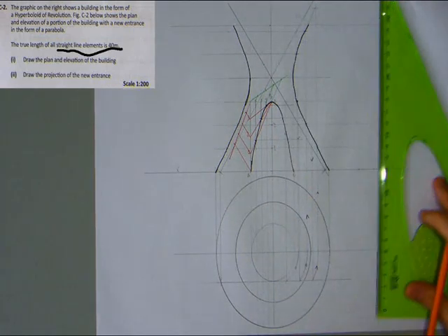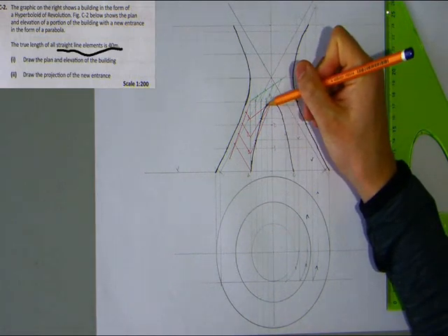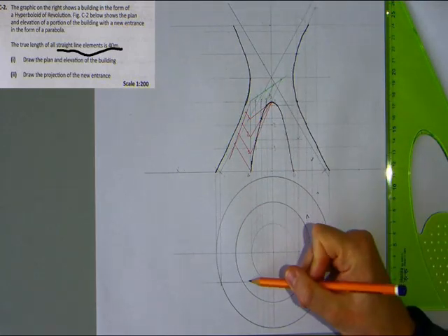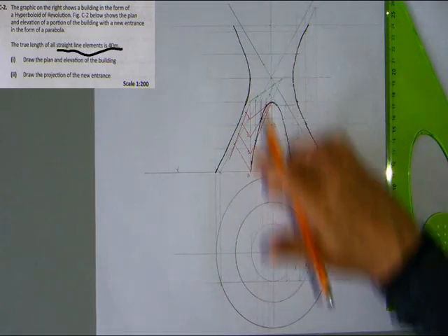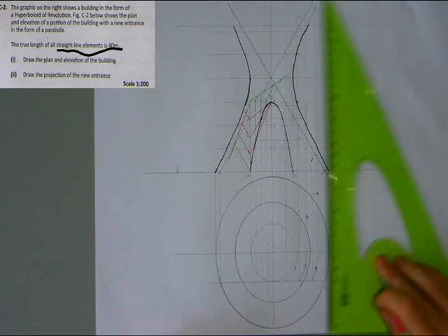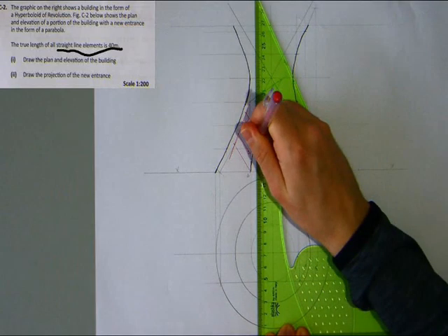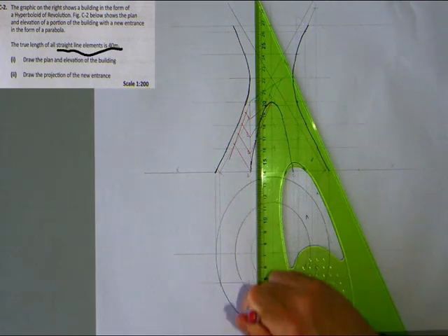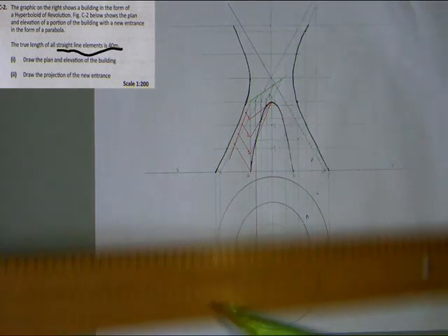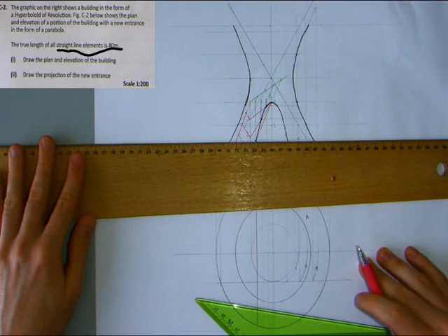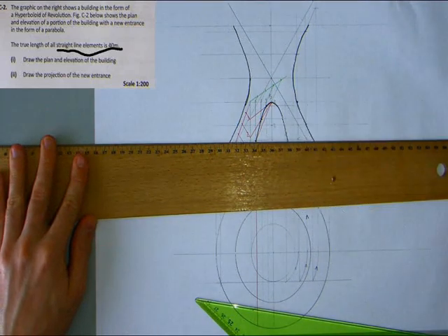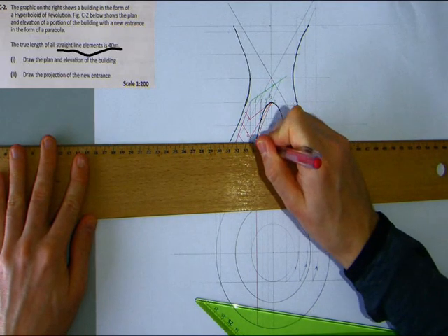What we're going to try and do is take those heights and bring them to the extreme generator down here and then rotate them to hit those corresponding lines. So what we'll do is, one has to be in this position. So again, I'm just going to do this in red pen, so we know it has to be in that position. So we'll bring it down straight. We'll take that position, we'll use a technique that we used earlier on, and we'll take that out to the extreme generator here.